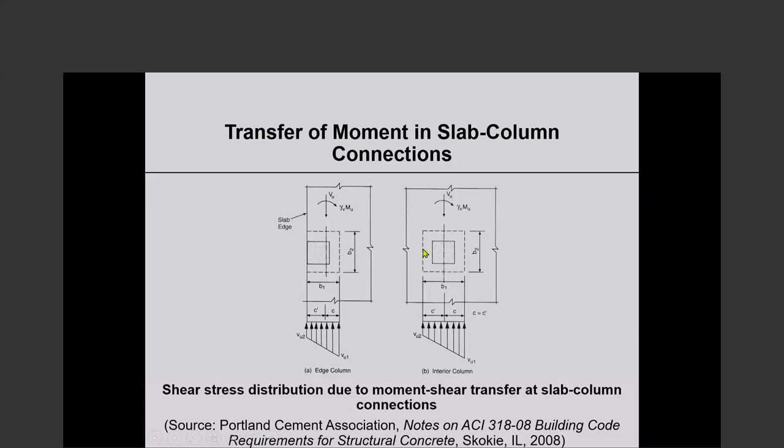On this face, the direction of the shear due to moment transfer will be opposite to the shear caused by gravity, so the stress from direct punching shear will be decreasing.